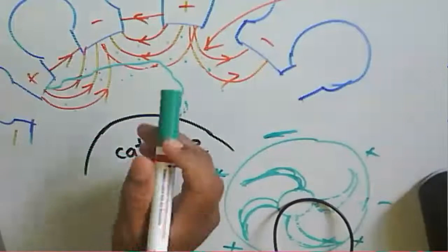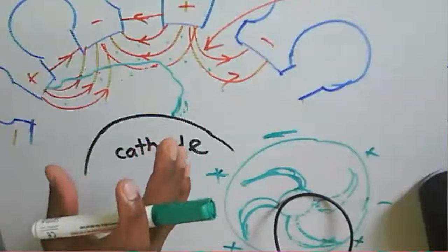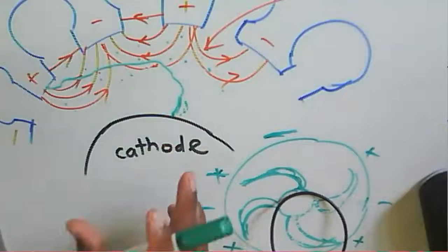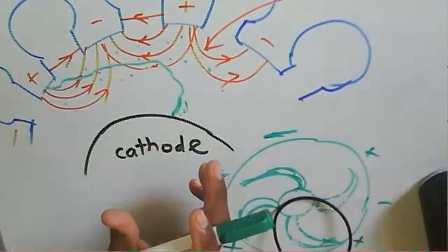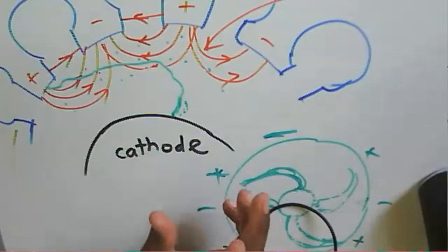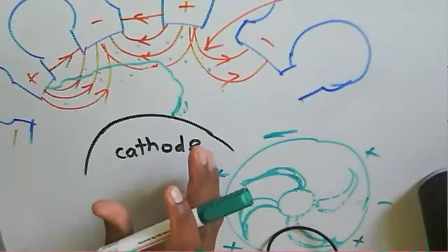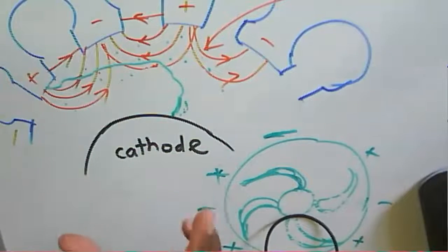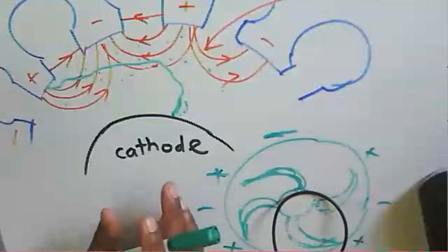Generally the power output by this magnetron will be large, up to 400 kilowatt or more than 100 kilowatt. The operating frequency of the magnetron is about 500 megahertz to 2 gigahertz, or in some cases we can achieve microwave frequency up to 10 gigahertz, and the efficiency of the magnetron is about 40 to 70%.